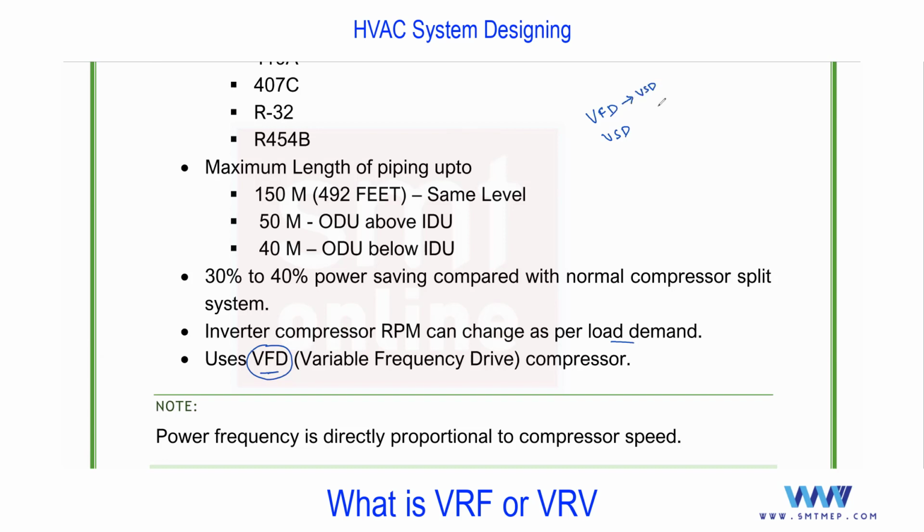Remember, this technology is for the compressor, for the pump, or for the fan. Pump means I'm talking about the chilled water pump or condenser pump, we'll discuss. And fan you'll find in the AHU and in the FCU. In that also you'll find this technology, especially in the AHU for power saving. So remember, if you find this VFD technology, by default it's a VSD.